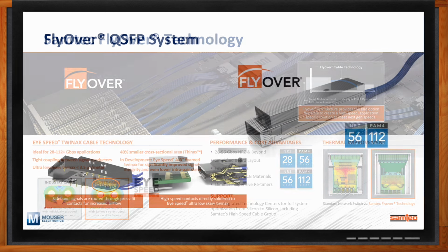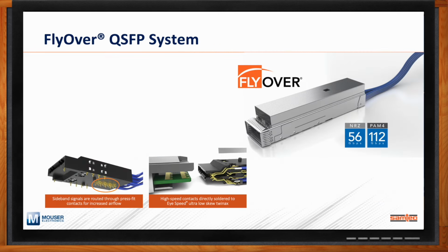So if you're using front panel, you need to have a front panel connector solution. So Samtec has a number of FlyOver QSFP systems that go into a traditional QSFP, QSFP-DD, QSFP-DD800. We're also looking at QSFP-DD1600 for data center applications. The QSFP solutions can support up to 100 gigabits per lane, which can give you 800 gigabits per port. We're looking at some of the next generation technology, which will get us from 800 up to 1.6 terabits per port. Some of the solutions, we offer double density versions.